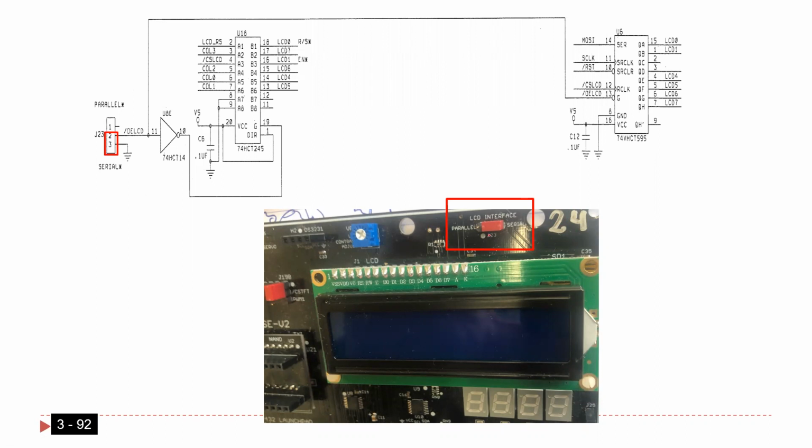you have to make sure, as you see here, guys, it's written serial and it's written parallel. In our case, because you inputted serial, you have to make sure the jumper is here. If you connect the other microcontroller, you have to put it here because it's parallel. It does not use a shift register. You got what I'm saying? You just write right away without a shift register. So you have to make sure, because if the jumper is in the wrong place, it's not gonna work. Everything is okay, but it's not gonna work.